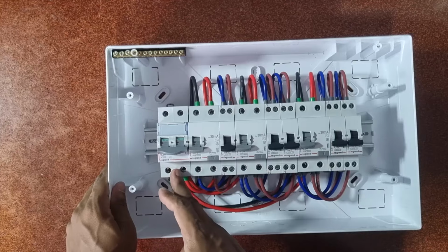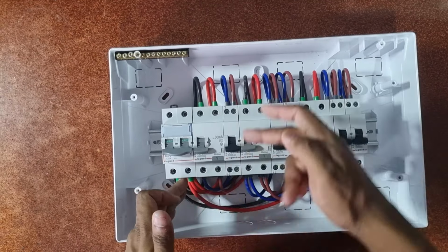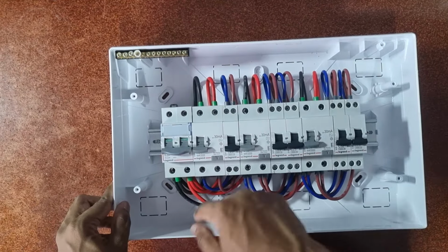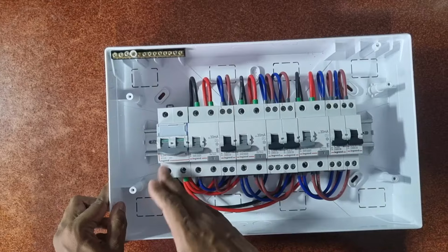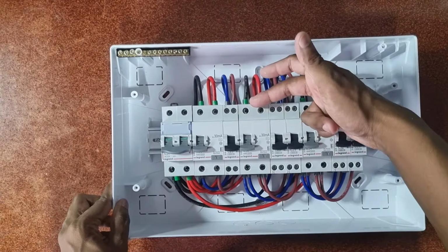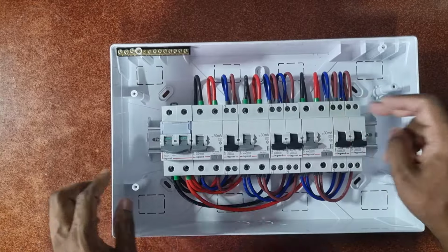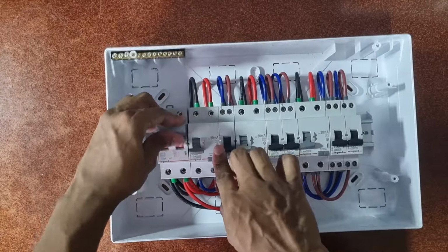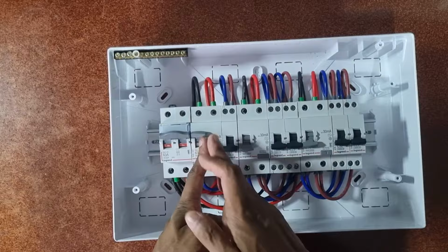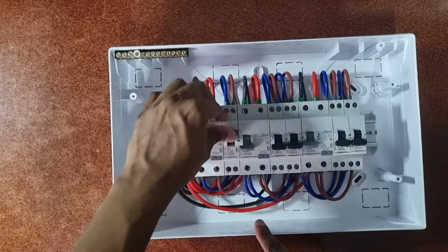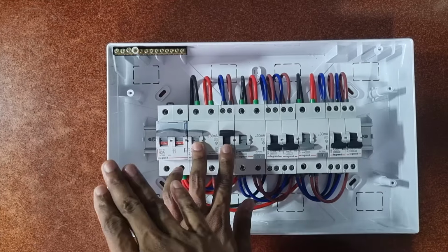Okay, so the wiring is very simple. From the output of the isolator, I just feed the 3 main RCDs, from output to input, again from the output here, and feed the input of this RCD, and the third one is also the same. Now when you switch on this RCD, it will control only the breakers after it. Okay, so when this is on, this one room is on.